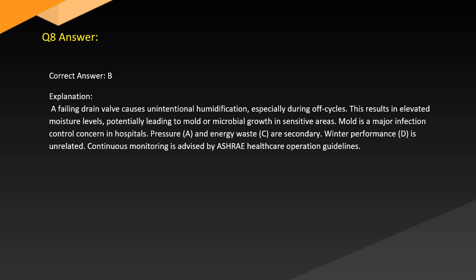Answer. Correct answer: B. Explanation. A failing drain valve causes unintentional humidification, especially during off cycles. This results in elevated moisture levels, potentially leading to mold or microbial growth in sensitive areas. Mold is a major infection control concern in hospitals.